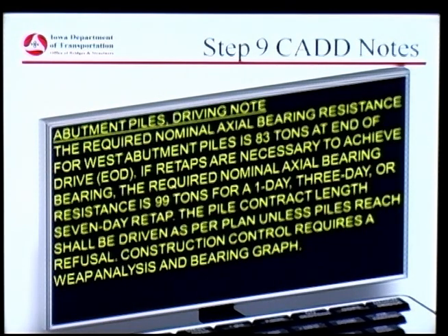Now, we need another set of notes in order to tell the guys in the field how to implement this, right? The idea, we're going to go verify the pile is okay. We need to know, well, okay, so what constitutes okay? Well, what we need is at end of drive here, 83 tons. If you can get me 83 tons at end of drive, mission accomplished, we're happy, go ahead, put your footer in. If not, then we need to do some more.